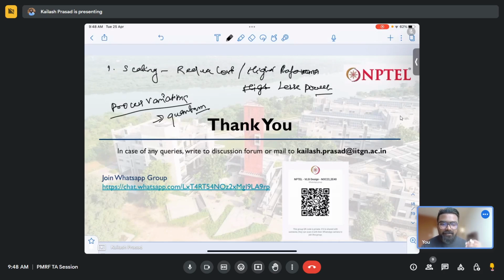There are challenges at the interconnect level. As you're narrowing down and down, many interconnects are coming closer and closer. Earlier, interconnects were far away, and if you ran something in one interconnect, it didn't have any impact on another interconnect. Now, as I have shown you in one of the slides, interconnects are so fast that if one interconnect switches, it impacts the other, because they are so tiny and very near to each other that the capacitance between them is extremely high, and the impact of one actually impacts the other, and it creates errors in the design.